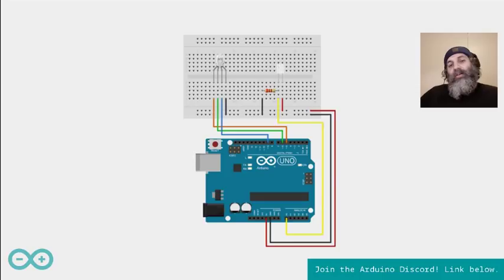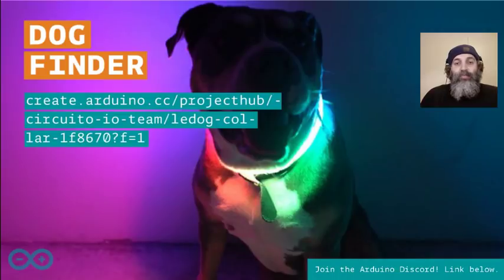This is the circuit view of what we're going to be doing. As you see, we're using a breadboard to connect the photodiode. For real, the RGB LED is not going to be connected like that, because if you remember, the module looks like this, as I was showing to you. So we don't need to plug it on the breadboard, even though we could. We're going to instead use some wires straight into the RGB LED so we can move it around freely. You will see very soon how it's connected to the Arduino board.